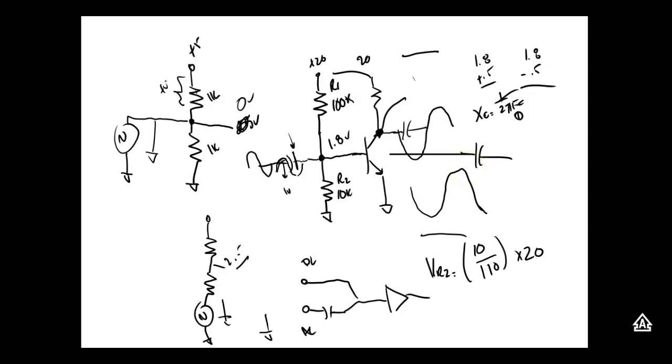These are called coupling capacitors, but we got one more thing to do. We demonstrated this the other day. This guy here, the beta would change with temperature. And we wouldn't want that to happen on our stereo. By the way, this is called voltage divider bias. You can see how I got this name, because we're going to bias the base up to a positive voltage, or negative voltage for PNP. And then our AC signal is going to add to or subtract from that. And hopefully, if we design it correctly, it will not saturate and it will not cut off. We'll talk about that too in the next class.